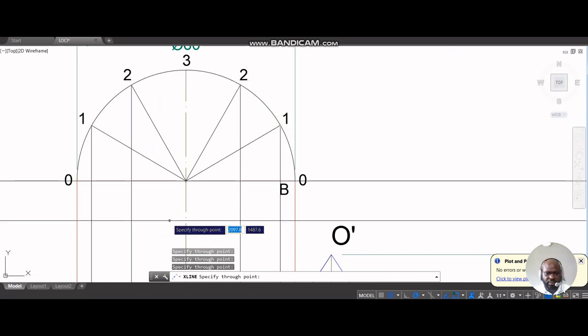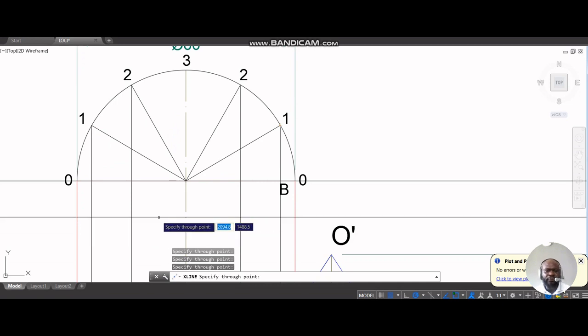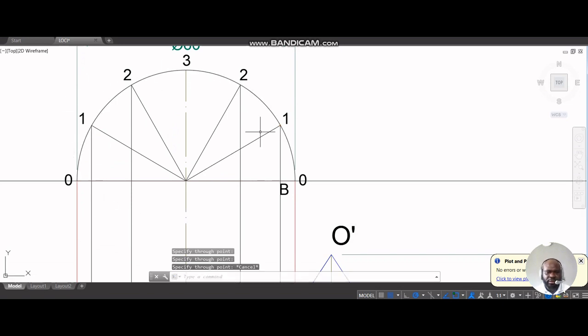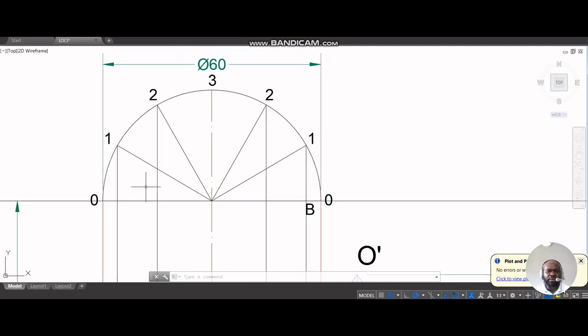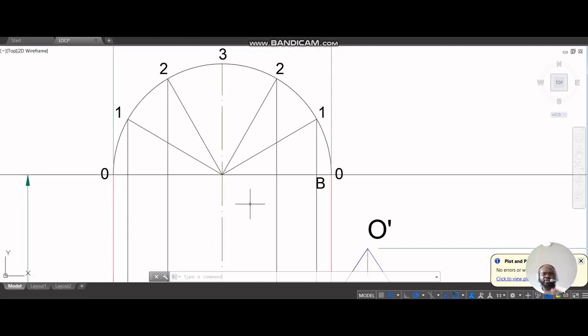All right. I think before I go further, let's consider this division. You find out that this division we have here is actually into 6: 1, 2, 3, 4, 5, 6. The gaps here are 6, even though we have the numbers alternating. What this also implies is that the part of the cylinder facing us is divided into 6.